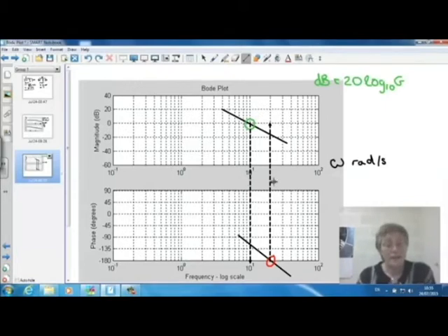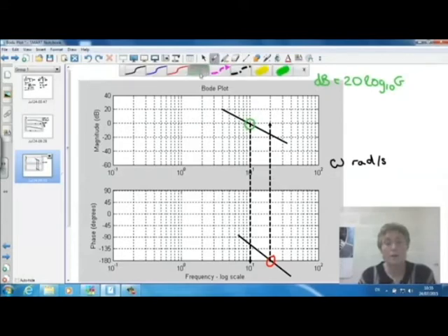So in this case, what we're now interested in is where on the gain plot we get minus 180 degrees phase shift. So that would be this point here. Okay, and reading off the scale here, I see that would be maybe minus 18 degrees or something like that. Sorry, 18 dBs.